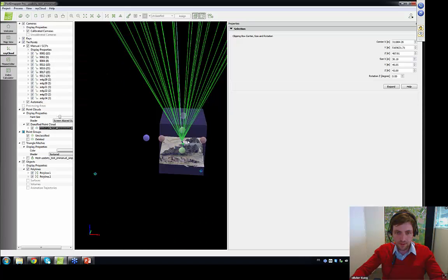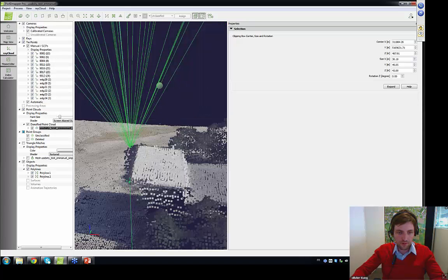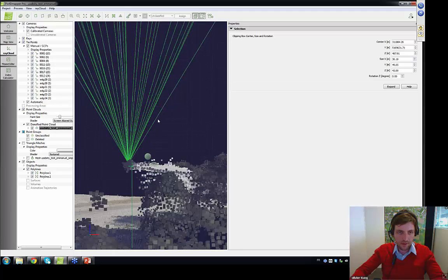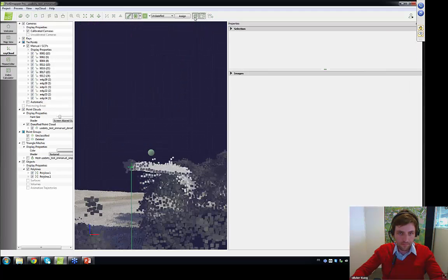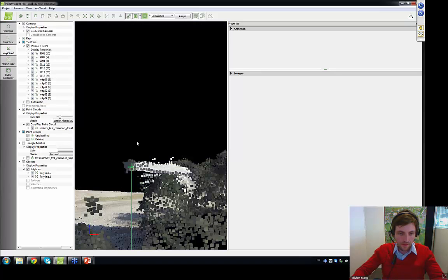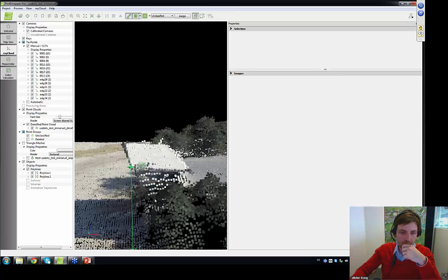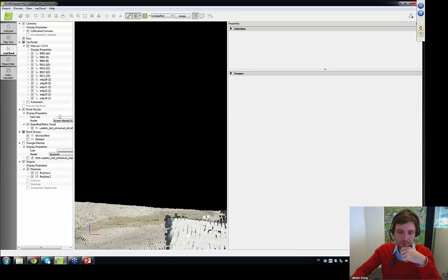You would activate the bounding box. Okay. Now you can look at it from the side nicely. You would click on editing the point cloud, and you would delete the points. And this way you just removed the noisy points.